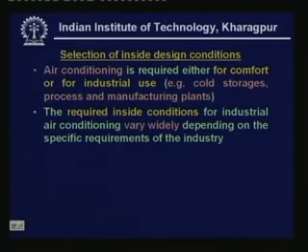So in fact there are many industries and many processes, many products being manufactured. So each product, each process requires different inside conditions. So you cannot have a universal criteria or universal value for inside conditions. Similarly for the cold storages, the required conditions inside a cold storage depends upon the type of product being stored, how long it is being stored, etc. Okay, so we cannot really generalize. So for these applications, that means essentially for industrial air conditioning applications, the inside conditions have to be chosen based on the specific requirement. Okay, when I say inside design conditions, what do we mean?